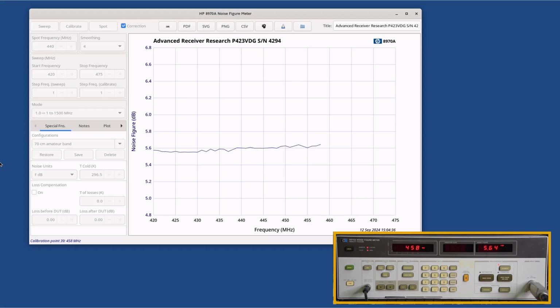Calibration is performed at 3 input gain or attenuation levels. During calibration, the display shows the noise figure of the measurement apparatus at that gain. On completion, the controls become active again and the corrected noise figure measurements can be performed within the frequency range.